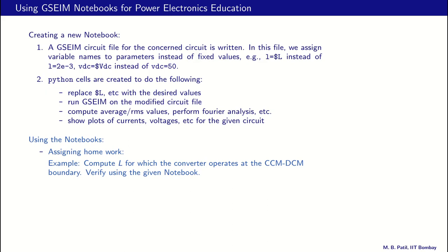In such a case, we can make up a notebook, and the problem statement then can be, for example, compute L, the inductance for which the converter operates at the CCM DCM boundary, and we share a notebook with them and ask the students to verify their results using the notebook.